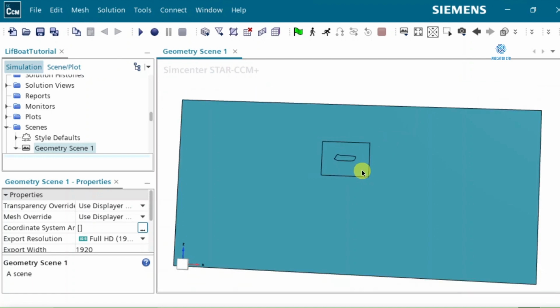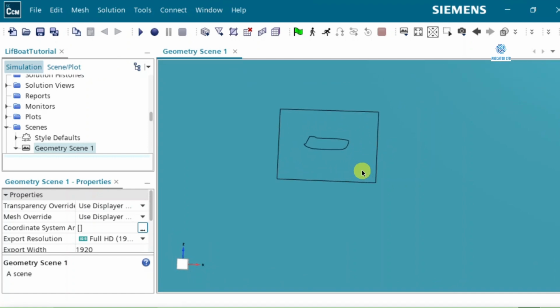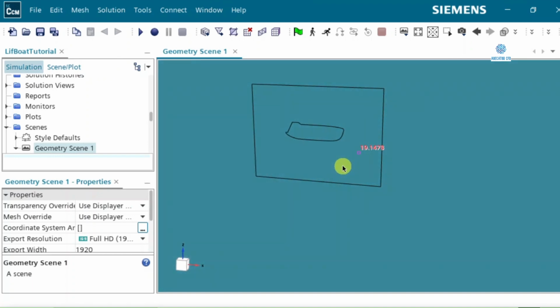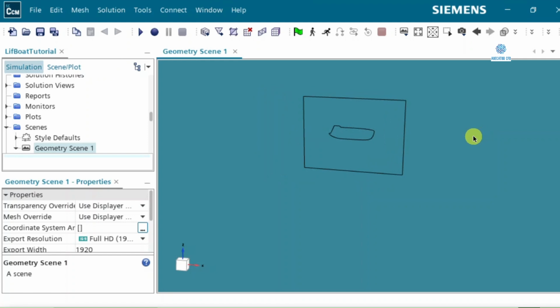The third point is also important. Around the hull, the mesh must be very fine. That fine mesh is needed to capture the physics correctly. Then, as we move away from the hull and toward the interface, the cells can grow. At the interface boundary, the mesh sizes should match the background mesh. Farther away, we can continue to coarsen the mesh toward the far boundaries.